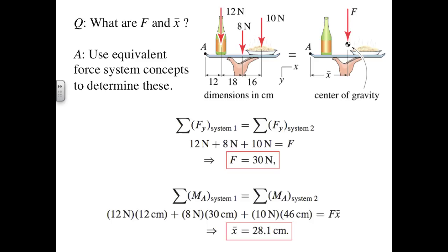The resultant force is just the sum of the weight of the three objects. The sum of the moments of these three forces about point A would be 844 Newton centimeters. For the somewhat unusual coordinate system sketched in the figure, note that the right-hand rule requires Z to point into the screen, so that in this particular illustration, clockwise moments exerted by these weights would be positive.